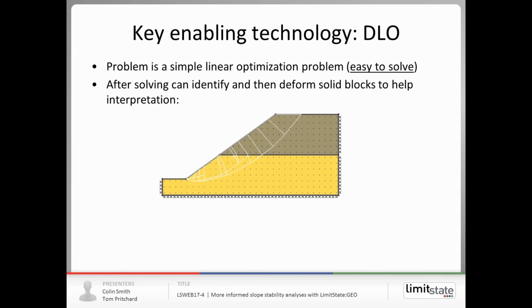the slip lines together and actually finds the elements so that it can animate those, to aid interpretation, so you can see how the failure mechanism is evolving. This animation is strictly only valid at the instant it starts to move, but we take it further than that so you can see what's going on. It basically gives you velocities of movement, but it cannot be used to determine displacements.